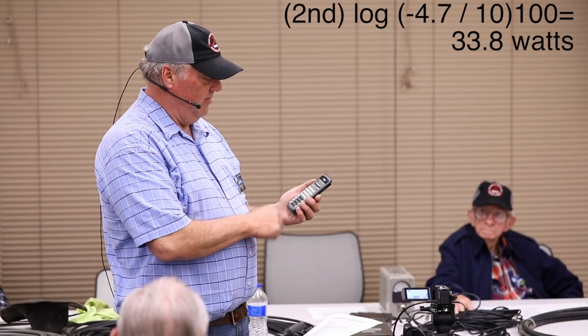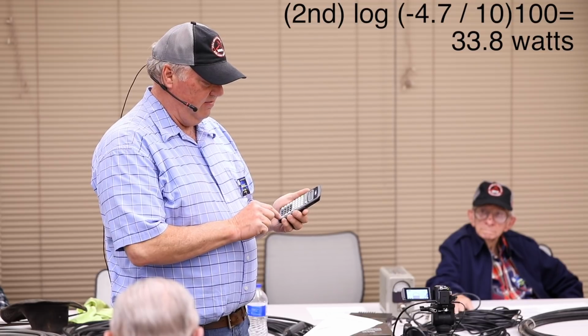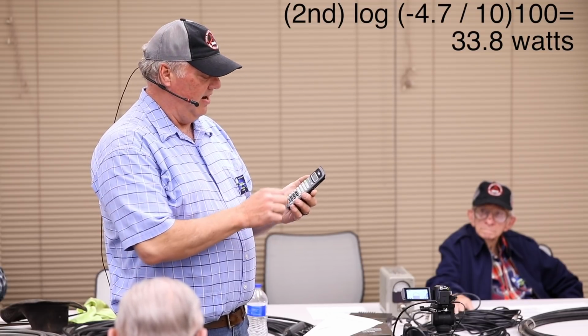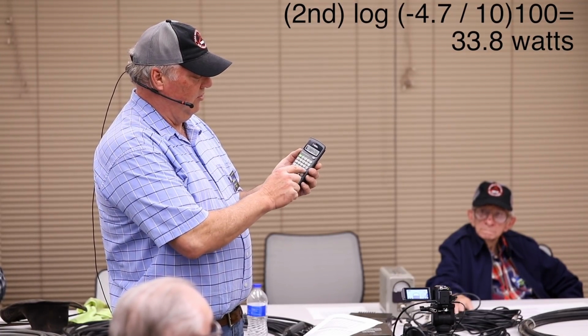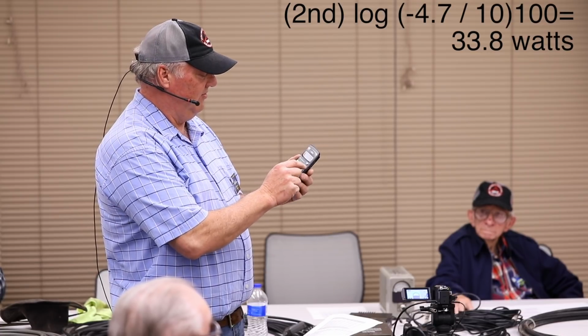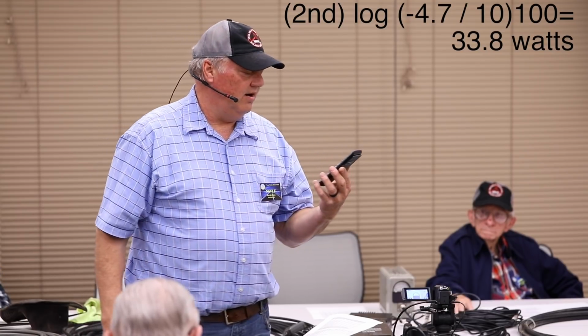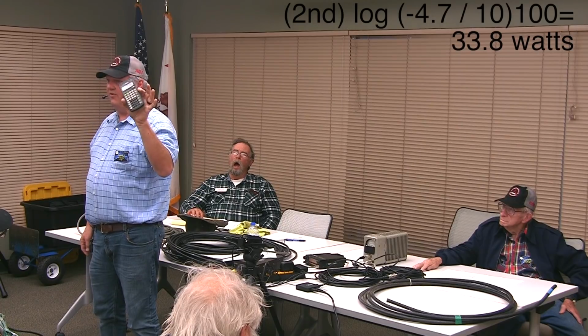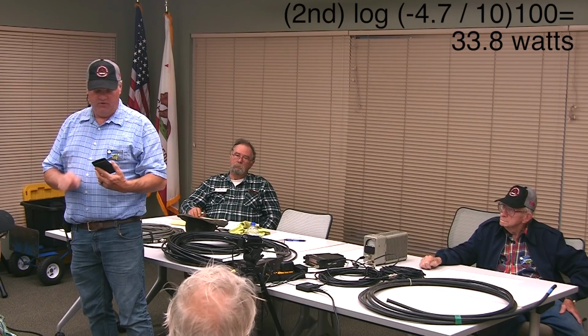You take the loss, that 4.7, and you make it a negative because it's a loss, and you divide that by 10. Then you hit the opposite of the log button, you hit your function, hit the opposite of that log button, and then you multiply it times 10. Or excuse me, I screwed up. We're supposed to multiply it times 100. That'll work. So I'm going to get about 34 watts, 34.2 something at the end. So you can look at the chart, and you can use the formula backwards so that you can get what your power is going to be.